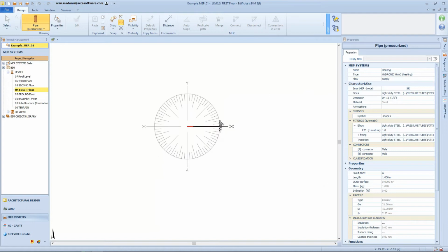In this way you have the possibility to choose different directions. If the direction of the pipe requires an angle that is not defined in the angle snaps, just move the mouse outside the protractor and fix the direction with a click of the mouse, based on the angle read along the circumference of the protractor, with an accuracy to the 100th of a degree. The angle can also be typed from the keyboard, or defined with a click in another point of the plane identified.